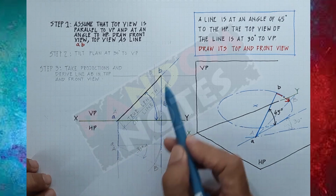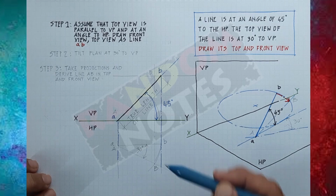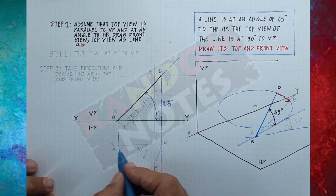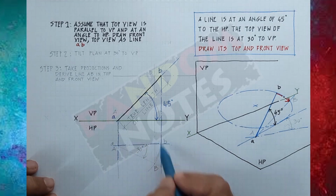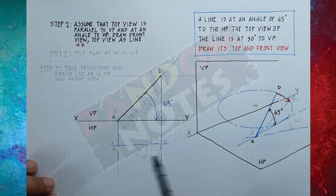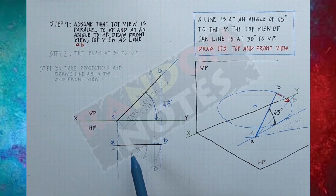From small a and small b, I dropped down 2 projections onto the horizontal plane, and at a given distance of point A from the vertical plane, I took another reference line. The meeting of these 2 projection lines and this reference line gave me the top view of the line AB, which I will darken. And this gives us the top view. So the first step has been taken.